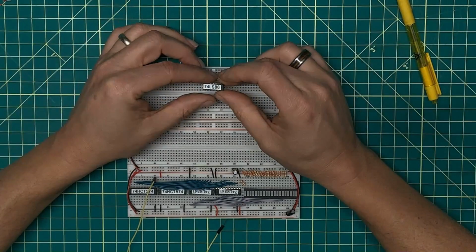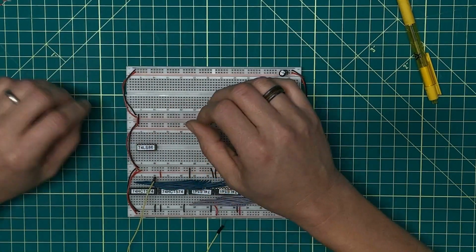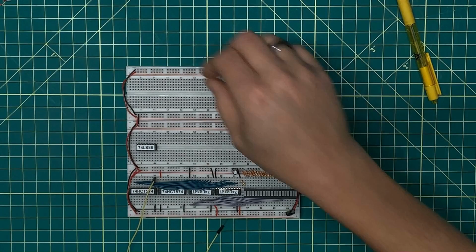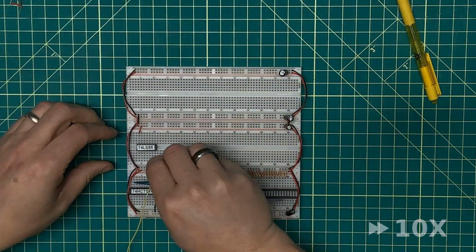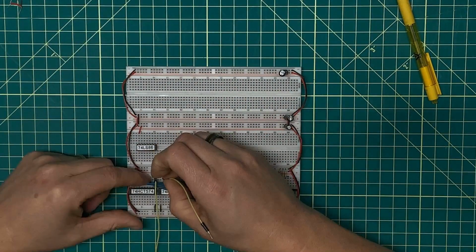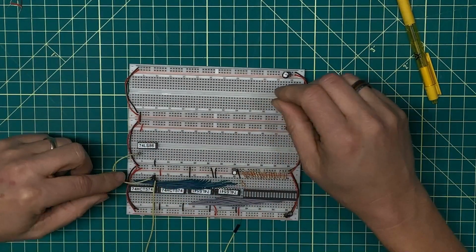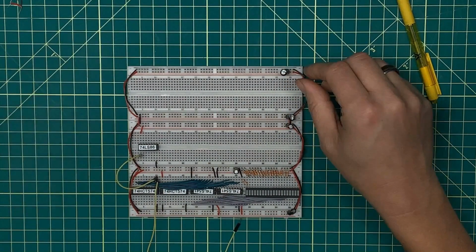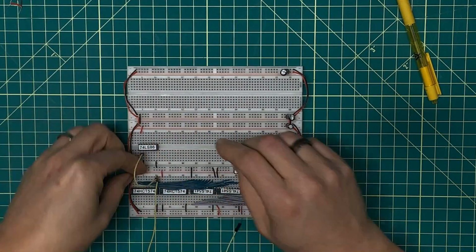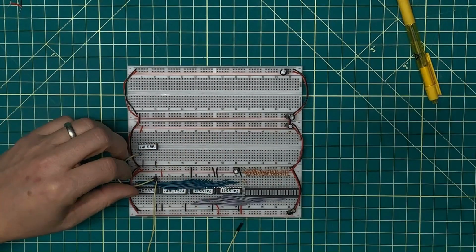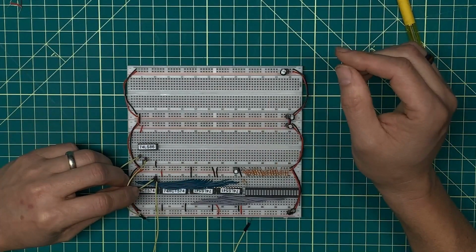Let's start with the 74LS86. This is going to be a quad 2-input exclusive OR. And then to that, I'm going to add power and ground. And then this is the clock signal that comes directly from the clock module. And I'm going to take that same signal and feed it into one of the inputs of an exclusive OR gate. Now I'm going to tie the other input down, so low. That turns this into a buffer. And then the output here becomes whatever it is I want to pass on to the rest of the control module.